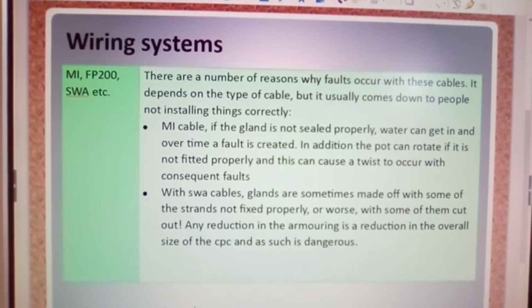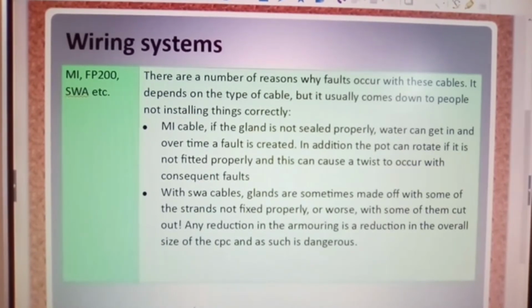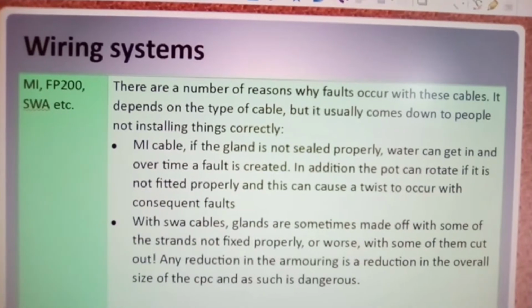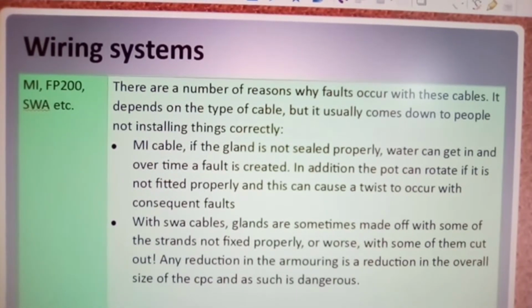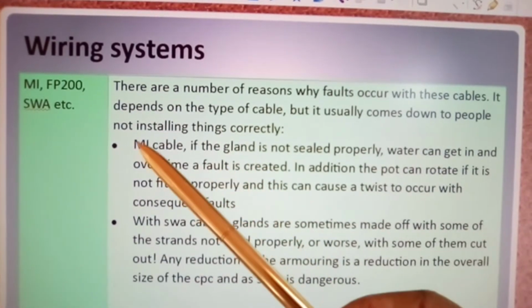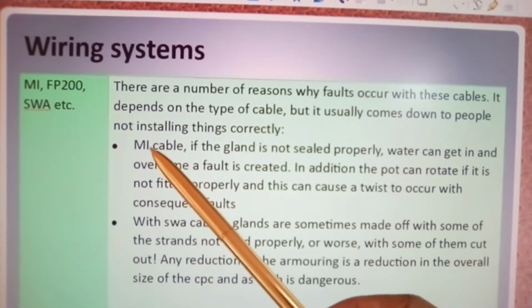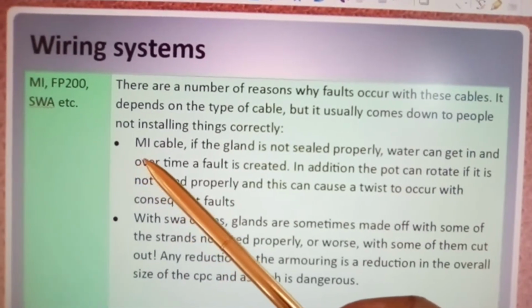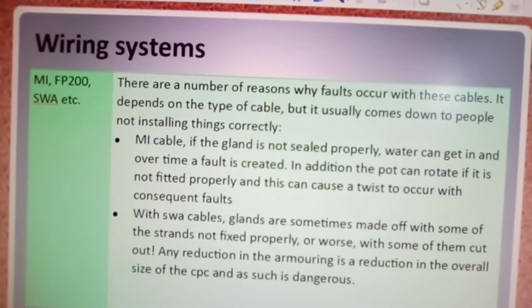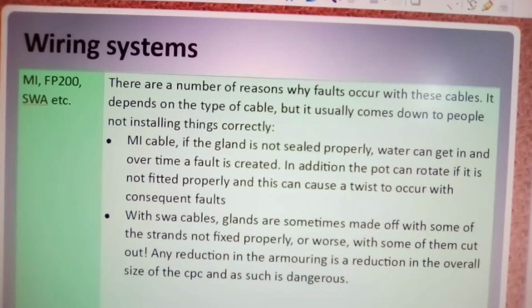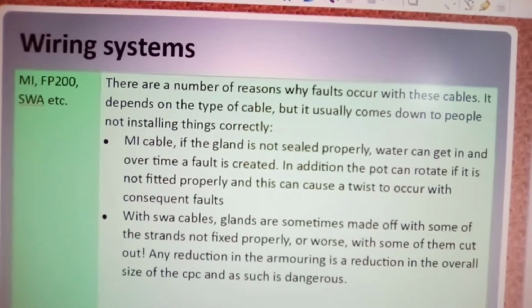That will tell you exactly what standards of fire resistant cables there are. And again, you have to read this for yourself. With MI cables, the making of the joints is very important. You make a mistake on these joints and they will short circuit and give you an almighty bang, especially if they're feeding motors, three-phase systems. It's important that you understand that.